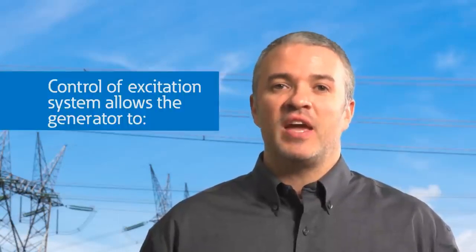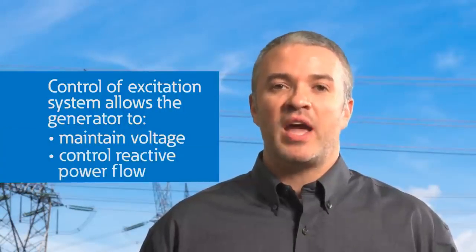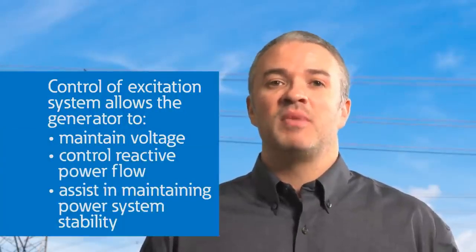The magnetic field strength of the field windings on the rotor can increase or decrease by changing the amount of excitation current. The amount of current and the number of turns in the field windings determine the strength of the magnetic field. The control of the excitation system allows the generator to maintain voltage, control reactive power flow, and assist in maintaining power system stability. During load changes or disturbances on the system, the exciter must respond, sometimes rapidly, to maintain the proper voltage at the generator terminals for the load.